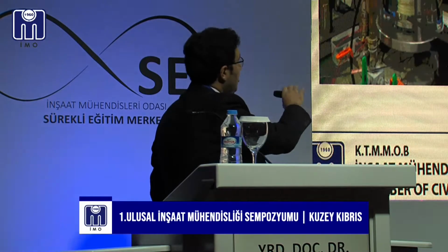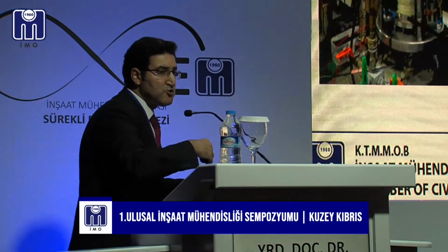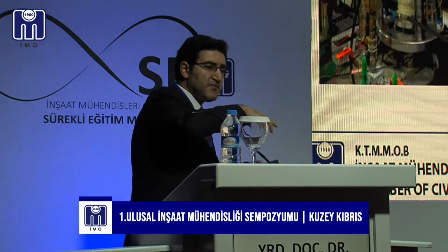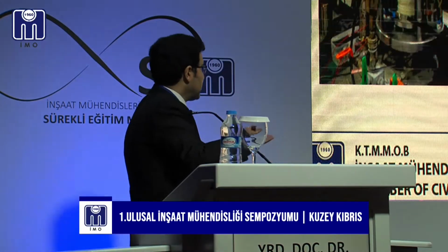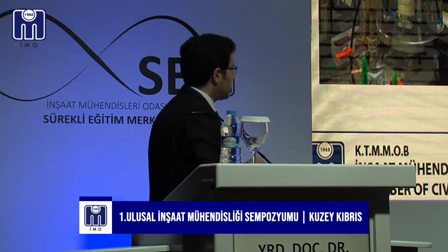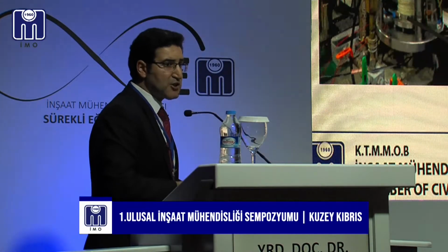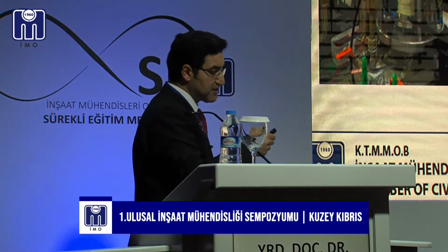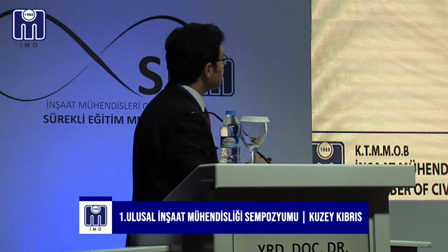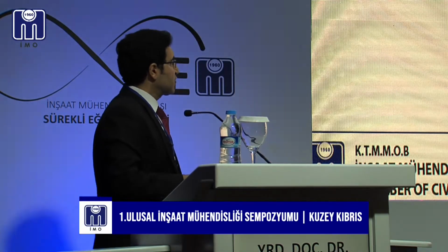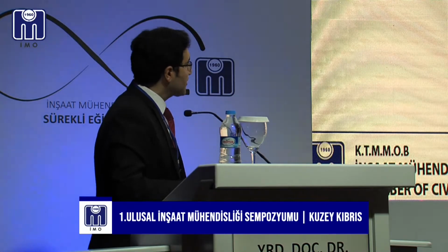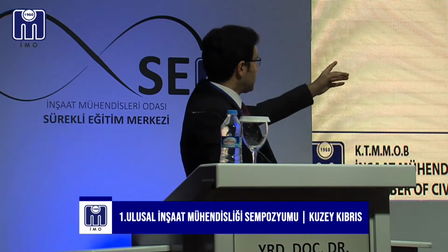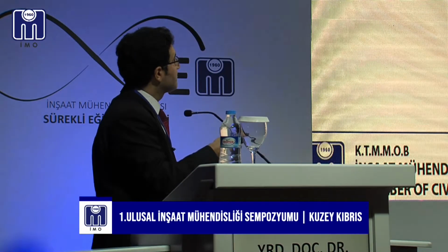There is no object going through the soil to disturb it: the top side makes a torsional impulse, and at the downside, in the pedestal, with a sensor we can calculate the transmission time, and based on that we find the shear wave velocity. And this is the downhole method, where we monitor the arrival of a wavefront with a receiver or geophone.